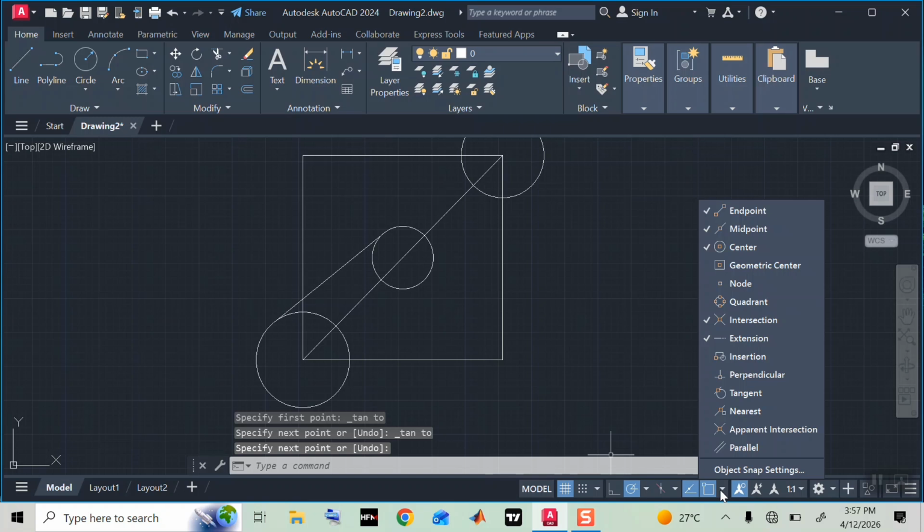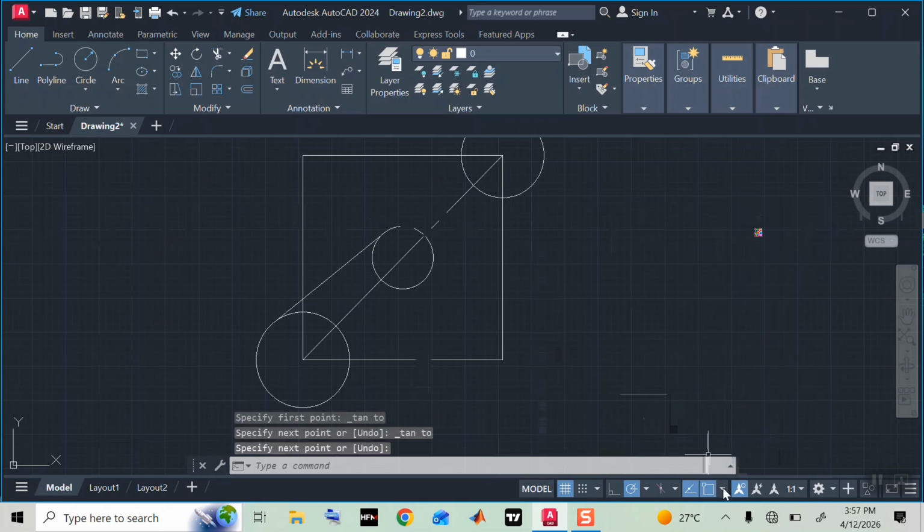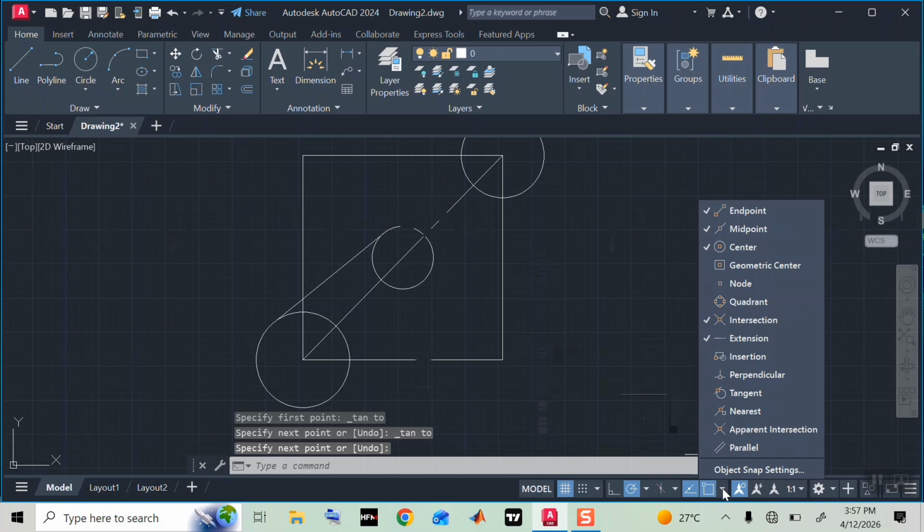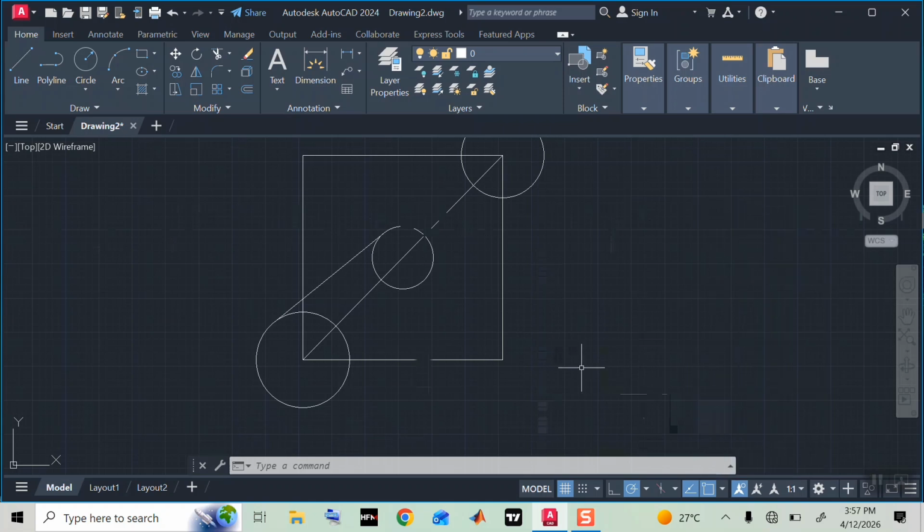Or we can just come here, this lower part. Let me show you again. Here we just select tangent. Instead of selecting the tangent each time, where we select the line, put on one point and then select again, you can just come here and select it for it to cut across. Then now come here and select this line at this point.